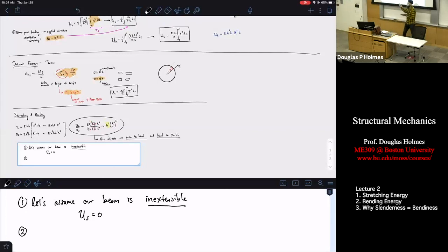This type of analysis also allows you to simplify your computational models. Now, you typically wouldn't throw away stretching energy if you were doing something in COMSOL or Abaqus or SolidWorks. But if this was a different type of energy, like gravity or something, you might say, oh, for my class of objects, if my length scale is small or big, I can neglect this term. That means I can run my simulation without including, say, gravity or whatever the term that is small.